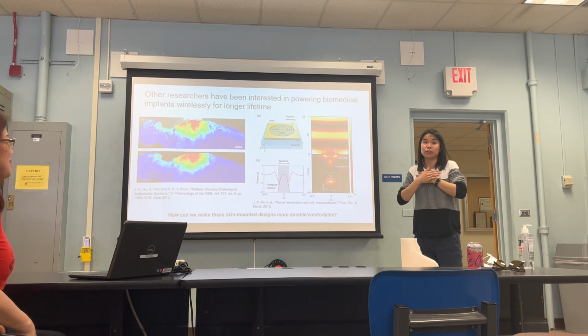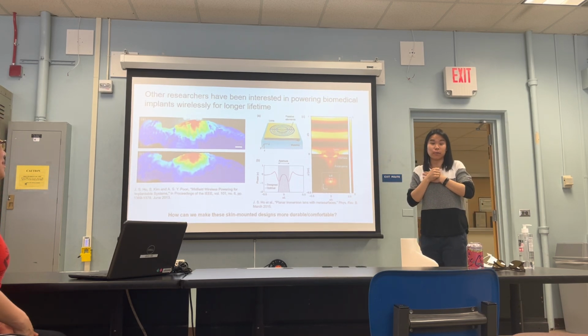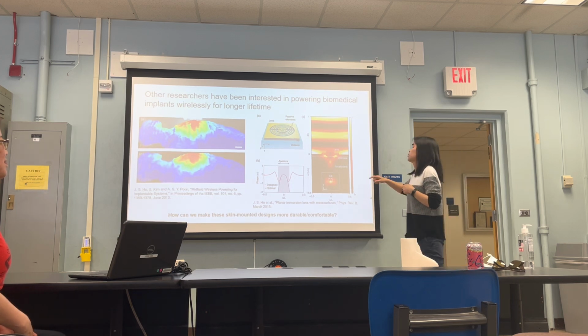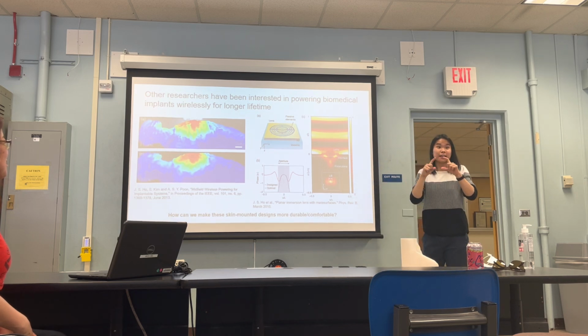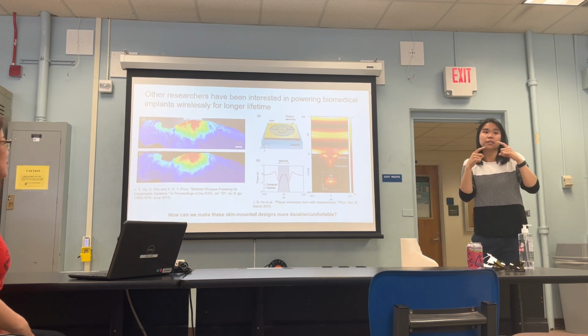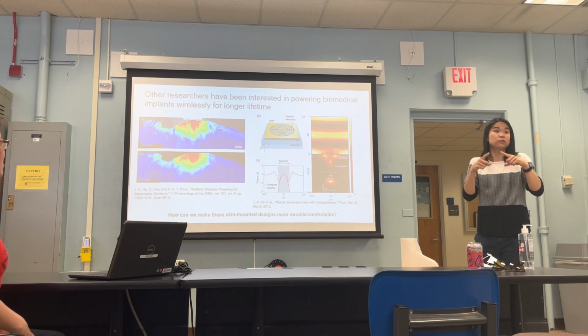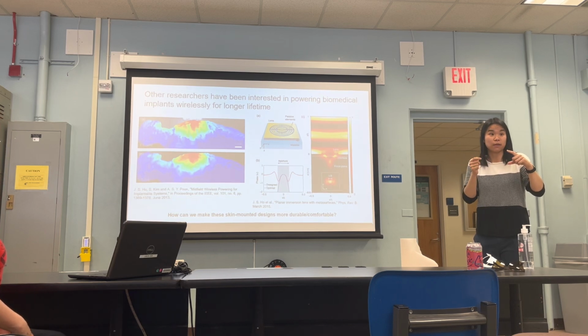But this is a case where you're trying to put something right directly against the human body. It has a different dielectric constant. You're trying to get focusing. So they came up with this design, which, if you guys are familiar with optics, like lenses, right? What if lenses can focus or disperse? So in lower frequency, you also use dielectric lens antennas. You can do the same thing to focus lower frequency EM waves.